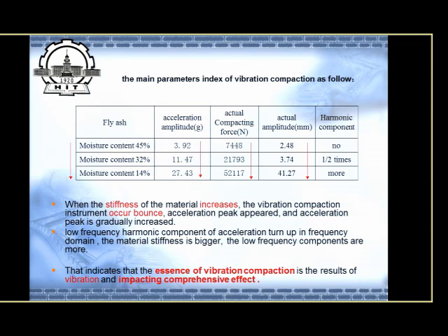This is the parameter index of the vibration compaction. When the stiffness increases, the acceleration amplitude increases, the actual compacting force is increased, and the actual amplitude is increased.